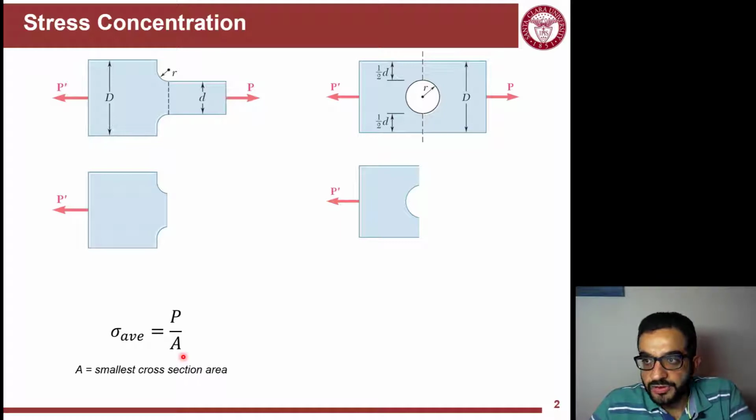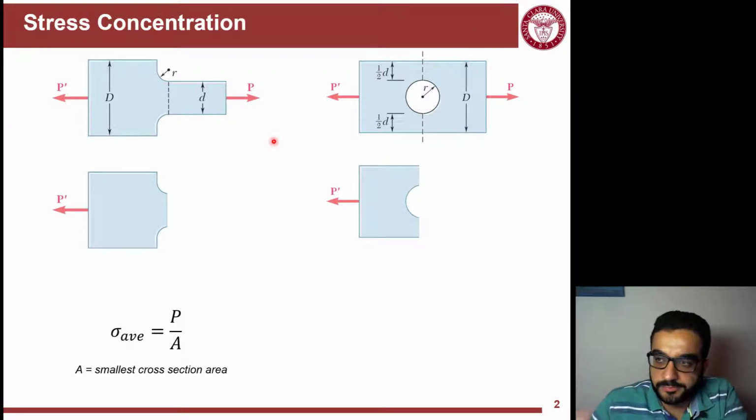So we're trying to see some special cases of axially loaded members. There are always changes in machining of members, and when you fabricate them and put them together in connections, you are changing the cross sections from bigger sections to smaller ones, or you're making holes for connections or for things you want to pass through the members. So making notches, reducing the cross section from D uppercase to D lowercase, or making a hole in the middle of the section.